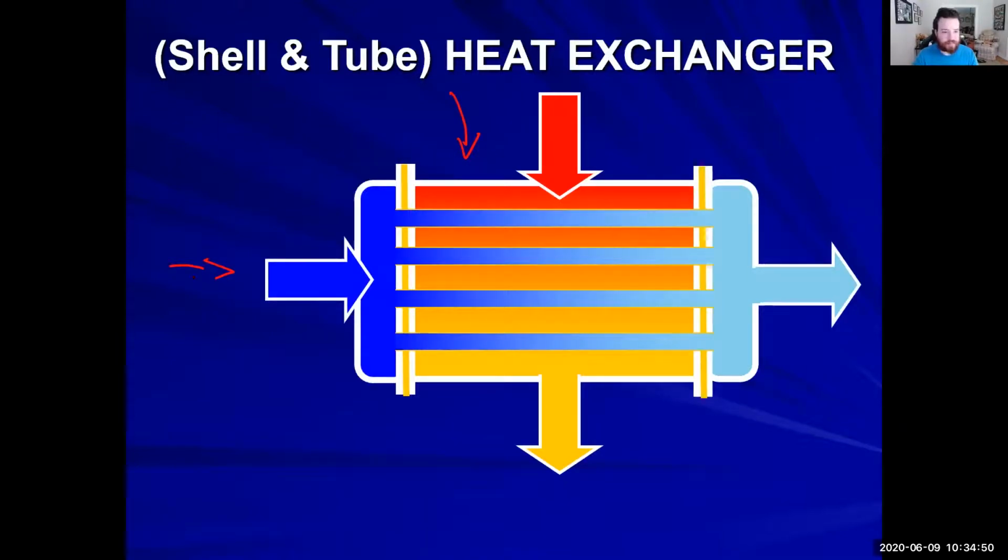All right, so we can utilize a saltwater pump, or we can utilize something called the scoop. All right, which is basically a scoop underneath the ship. It's just a port that scoops up water, and it uses the ship's forward momentum to push water up through the condenser and out the other side.